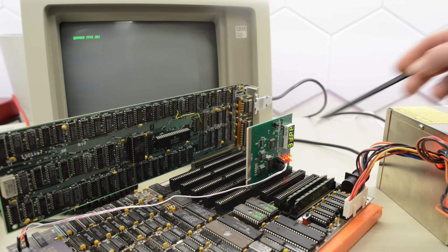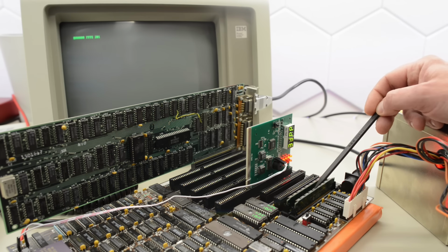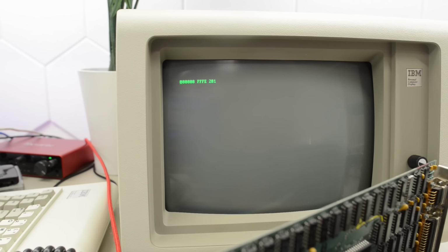If you don't have a set of extra SIMs, you could move SIM 1 to the SIM 2 slot and SIM 2 to the SIM 1 slot. If you get a different address in the error, then you know one of the SIMs is bad. But in this case it didn't make a difference.